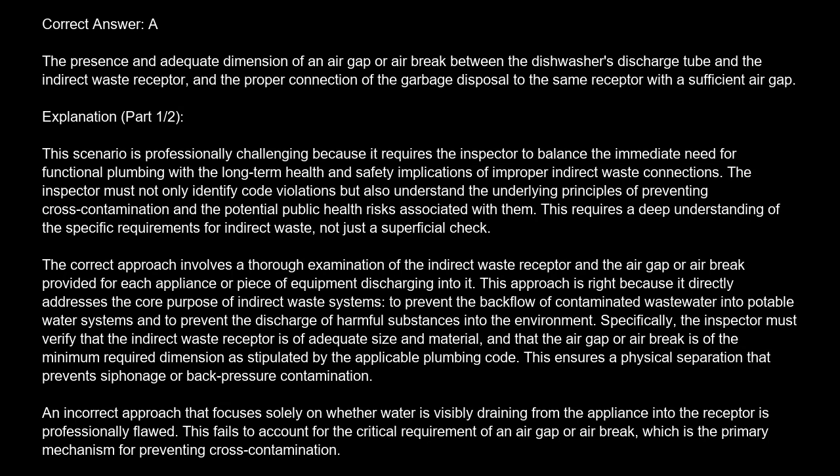The correct answer is A. The presence and adequate dimension of an air gap or air break between the dishwasher's discharge tube and the indirect waste receptor, and the proper connection of the garbage disposal to the same receptor with a sufficient air gap.